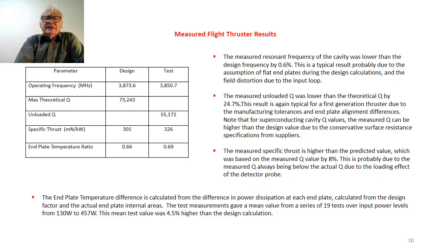This Q that we measured was actually lower than the real unloaded Q of the cavity, because our measurement was done at the input of the cavity, and we were unable to take into account the loading effect of the detector probe.